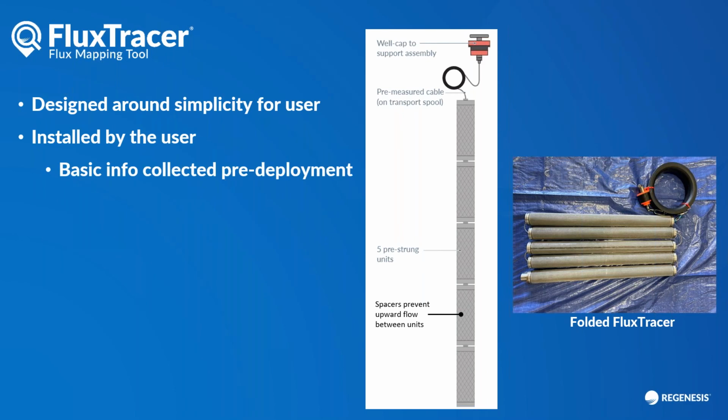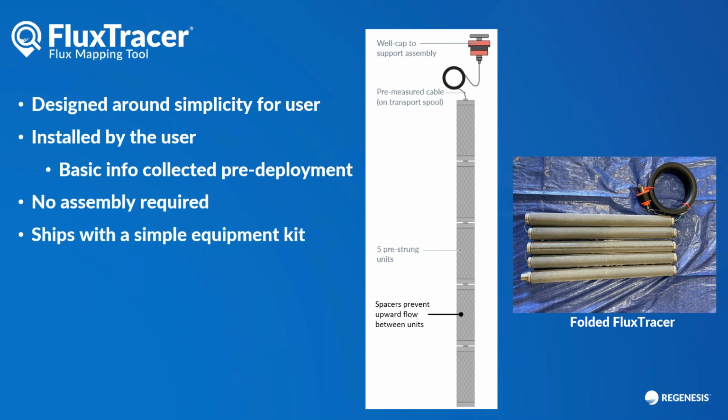And the devices are installed by the user. So what we'll do is collect some basic information that we need from you about the well: the depth, the type of contaminants that you're interested in, and the well construction materials. And then, very importantly, the depth that we're deploying this device to. All of this information is gathered up front. What that allows us to do is send a device that doesn't require any assembly once it gets to the field. So the device is really ready to go.